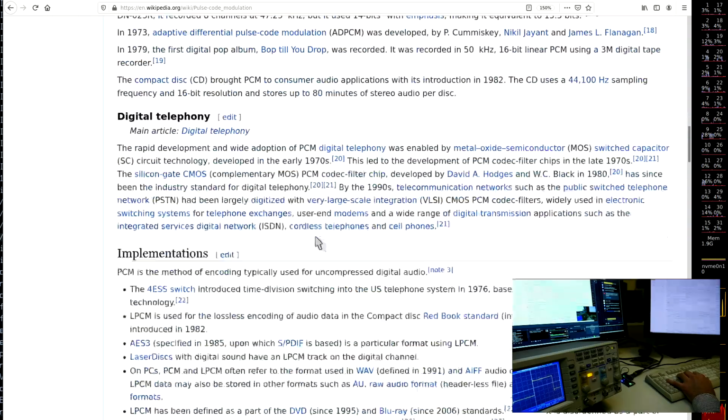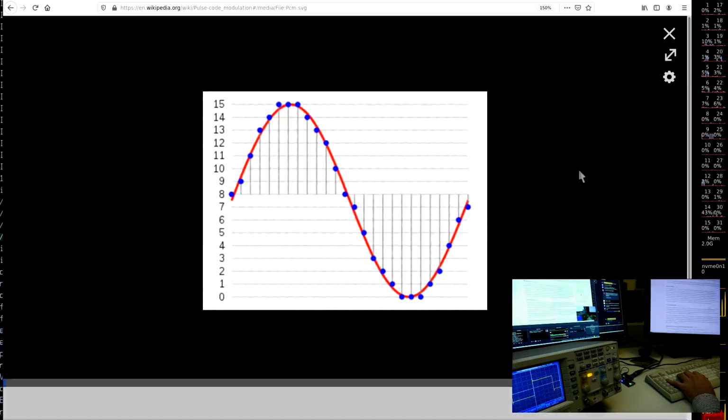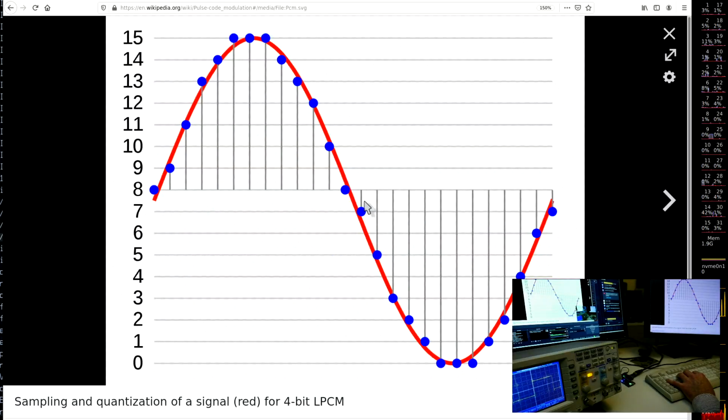This means you have some samples at a sampling rate of, for audiophile CD goodness, 44.1 kilohertz, and you can certainly reconstruct any waveform up to a frequency of half the sampling frequency with the Nyquist theorem, and that is how we usually would do it.